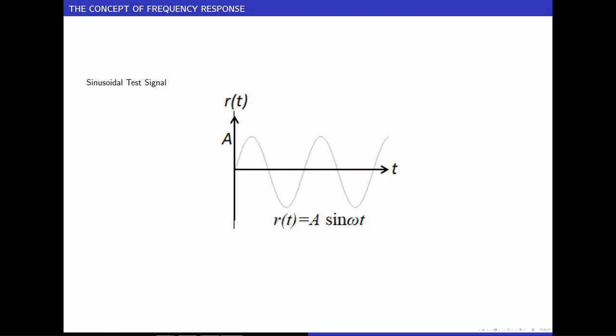You might have studied in Fourier transform or Fourier series that any periodic input can be expressed as a sum of sinusoidal signals. Therefore, even if I want to analyze a mechanical system or an electromechanical system for any periodic signal other than sinusoidal signal, I can resolve those periodic signals into sinusoidal signals, and I can give those sinusoidal signals as the input to the system and analyze the system. Therefore, sinusoidal signals are very important signals to test the performance of any system.